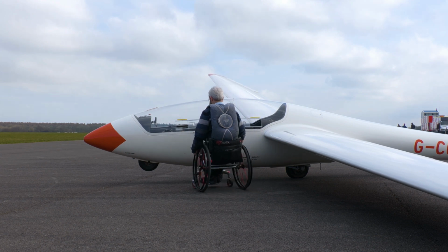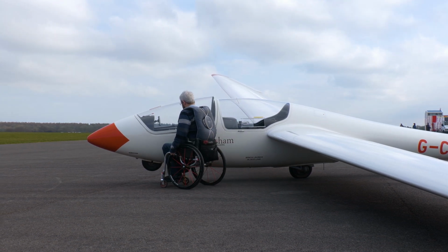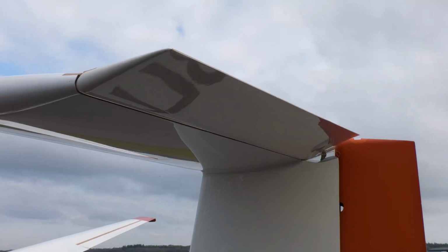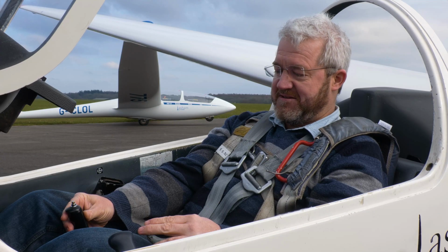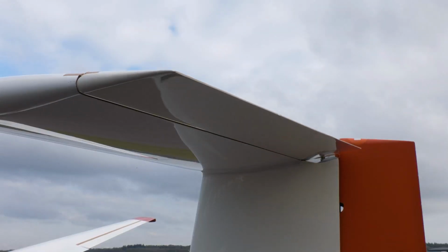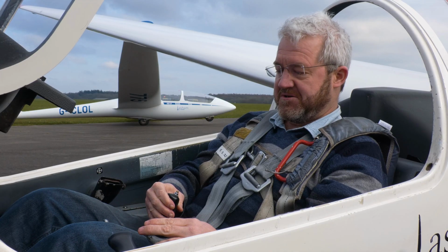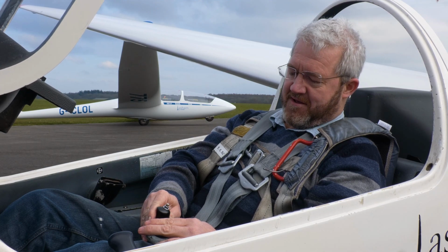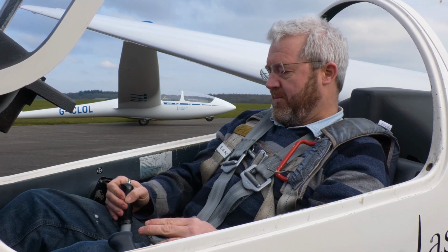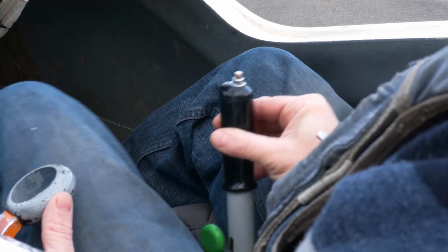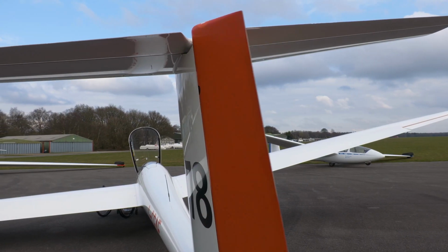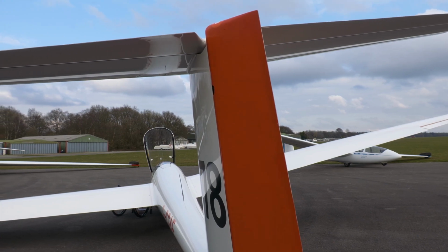So in the cockpit we have the primary flight controls. The stick in the glider: when we push the stick forwards, the elevators change position. We pull the stick back, the elevators change position. We roll the glider by pushing the stick to the left, the ailerons move, and to the right, the other aileron moves. The rudder is operated by pushing the rudder pedals.